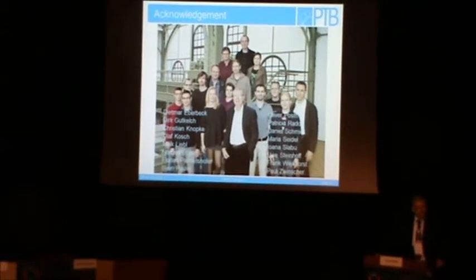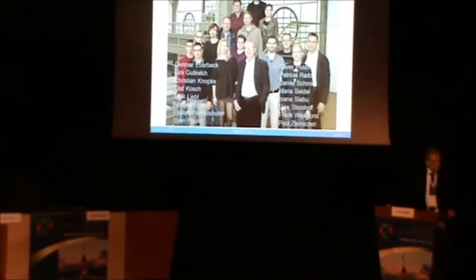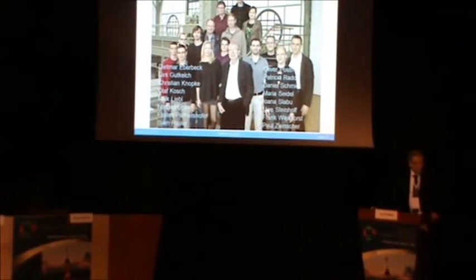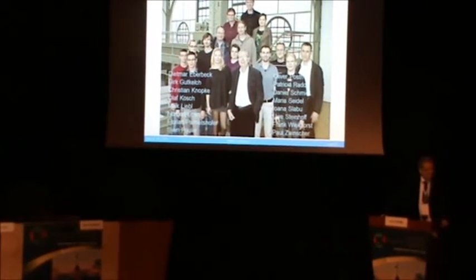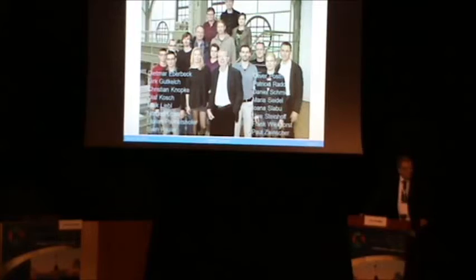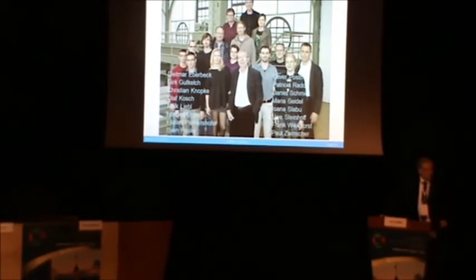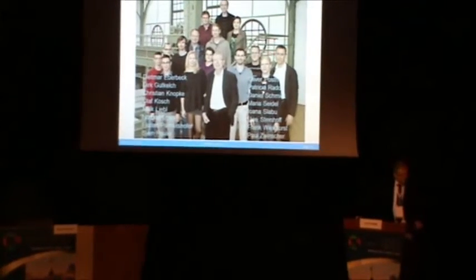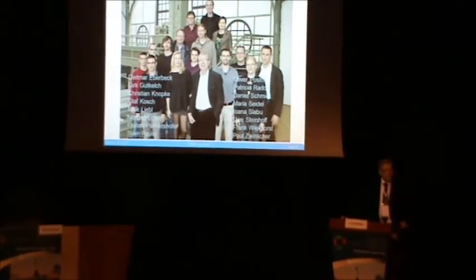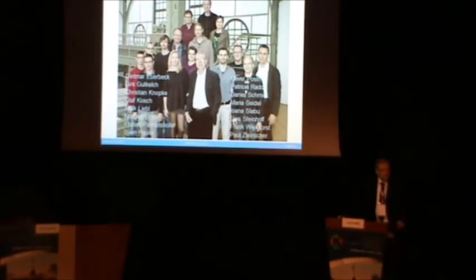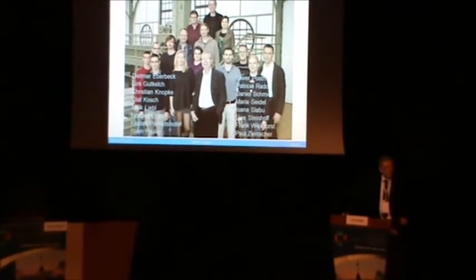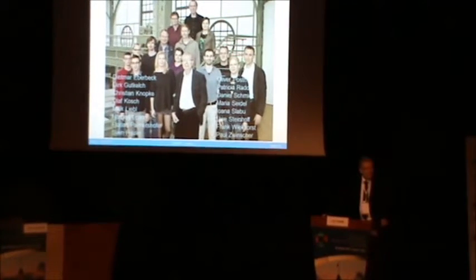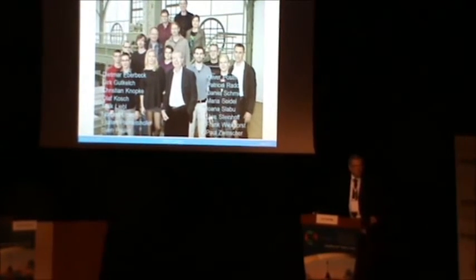Thank you for that. Regarding the SQUID relaxometry, I have a question. The sensitivity of this SQUID is 6 or 7 orders of magnitude different from the applied polarizing field. So in that case, how are you preventing flux trapping in the SQUID? Do you polarize remotely and then move, or use some switch or current limiter in the flux transformer?